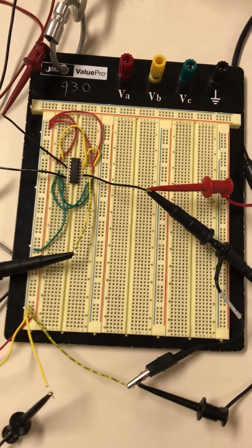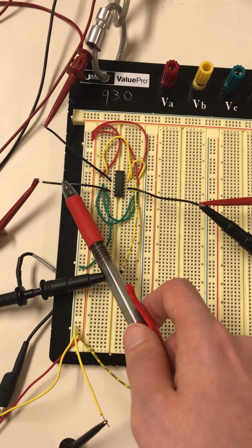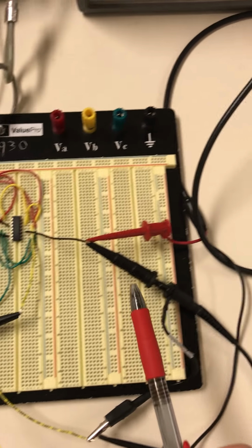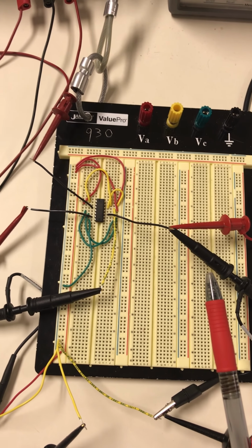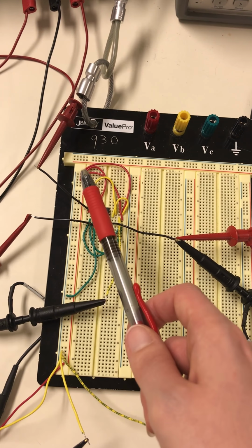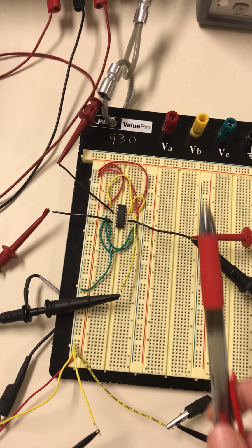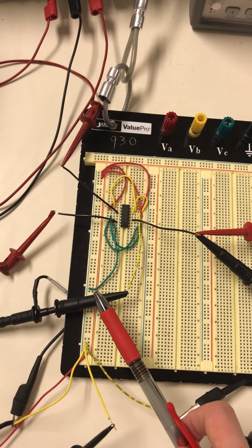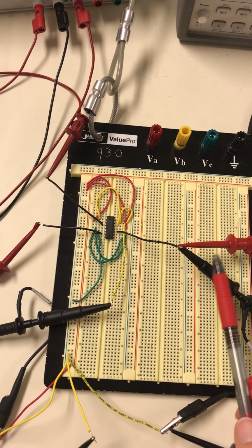So this is the circuit that I built, and this is my IC. The connections are made. V1 is connected to here. This is my V2, and this is V3 that comes from the function generator, which is set to generate a square wave with the amplitude of 0 to 5 volts. V1 and V2 are right now connected to the 5 volt DC power supply, and I'm taking the output from pin 12 that I'm going to show in channel 1 of my oscilloscope, and V3 is connected to channel 2 of my oscilloscope.